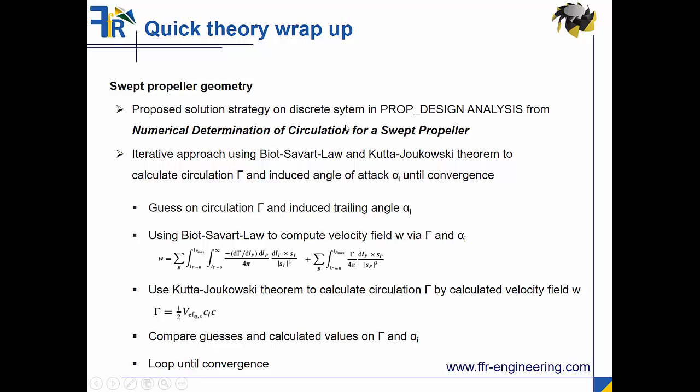So for example, in the original paper it stated that you cannot have wake contractions, so you really have those vortices from the trailing edge remaining bounded there like a line, but in reality this is not the case, so they are turning to be unsharp, you have some turbulences, and so on. And this is not considered in the paper. Anthony Falzone states in his code that he considered the effect as well, and the effect is minimal, but it's also partially considered in his implementation.